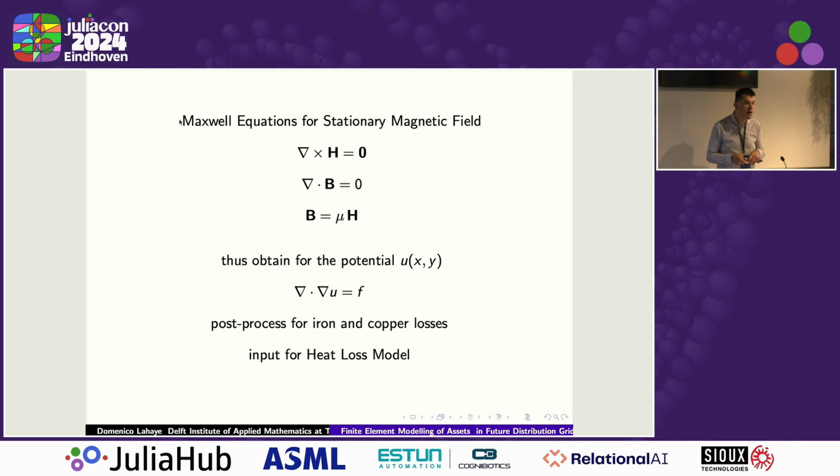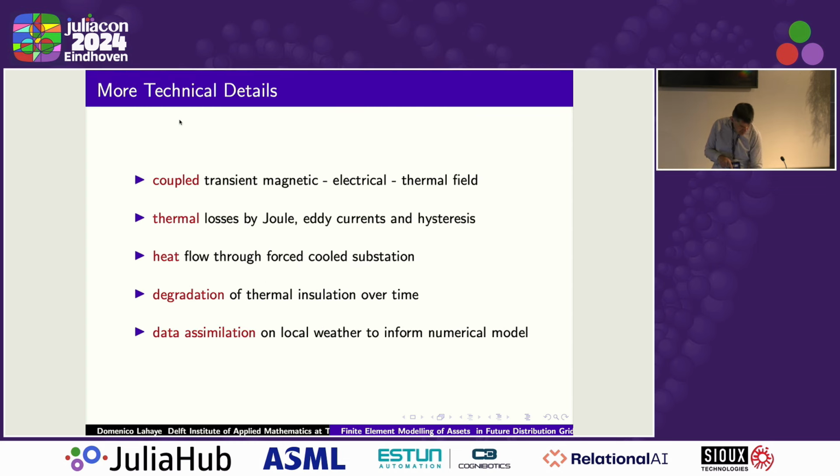Are you then also implementing your own ODE solver, or how are you doing this? Not yet. We are relying on the tools that the package provides to do the time-varying case. However, in reality, the transient case is difficult because we also have to take into account the algebraic constraints coming from the circuit. So we also need DAE solvers to be able to do the transient simulations. Okay, thank you.